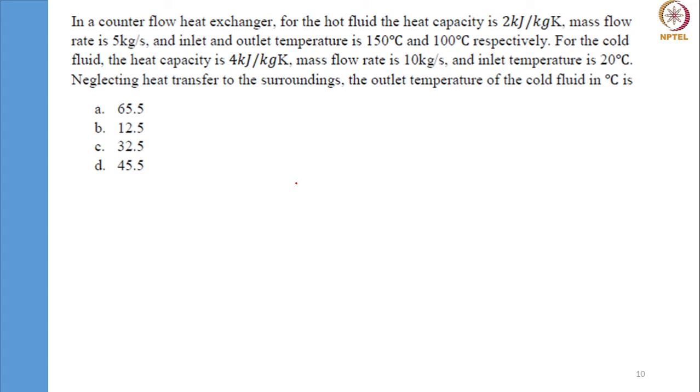We have a counter flow heat exchanger where Cp of the hot fluid is given, the mass flow rate is given, the inlet and exit temperatures are given, the cold fluid heat capacity is given, mass flow rate is given, inlet temperature is given, the exit temperature has to be known. So you can apply the first law of thermodynamics, that heat lost by the hot fluid is equal to the heat gained by the cold fluid, and